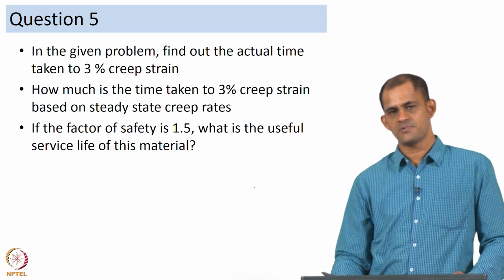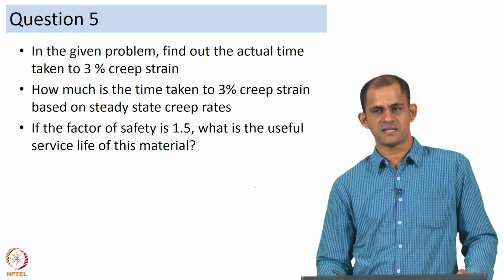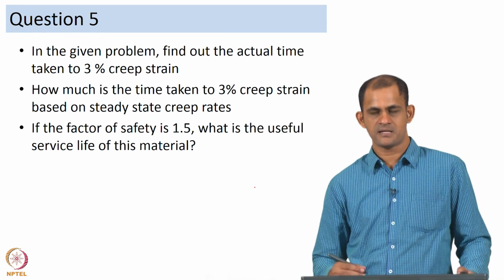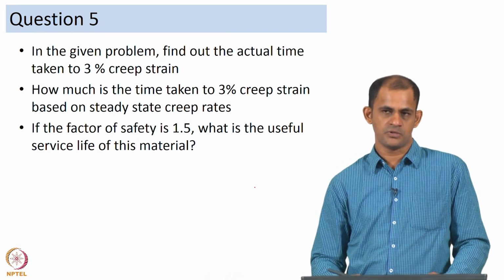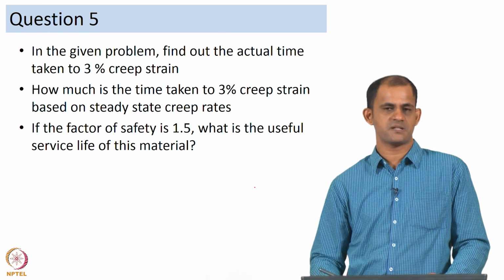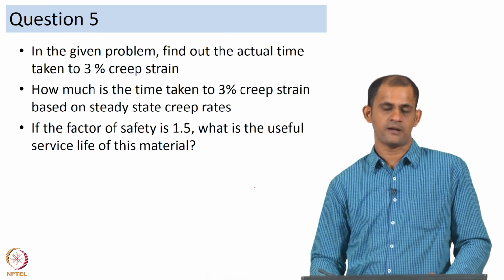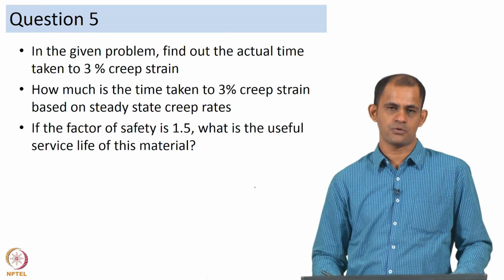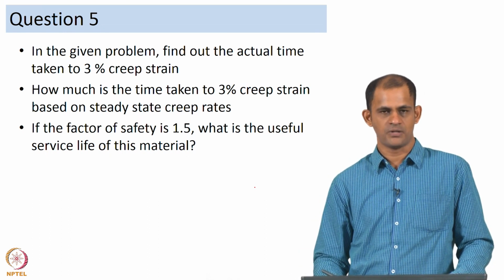Now, a lot of times engineers tend to design their components based on the steady state creep rates. The reason is you can achieve your steady state creep rates. Typically creep experiments can last very long, and by the time you go to a tertiary creep regime and failure, it may take you at least a few hundreds of hours.